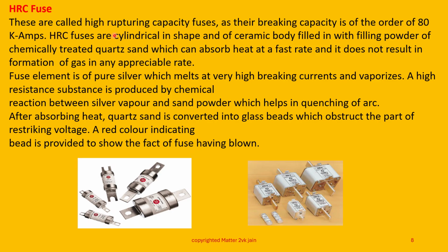HRC fuses are cylindrical in shape and of ceramic body filled in with filling powder of chemically treated quartz sand, which can absorb heat at a fast rate, and it does not result in formation of gas in any appreciable rate. Fuse element is a pure silver which melts at very high breaking currents and vaporizes.